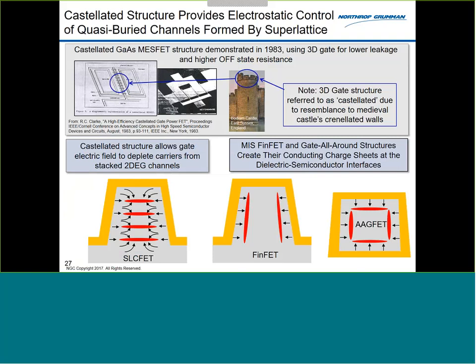In our device, we're using the gate here on these sidewalls. This guy doesn't do anything because of the shielding effect, right? So all my action is from these edges. If I just made a Schottky gate right there, this wouldn't work because I'm showing there's some depletion here, but essentially I'm making a practically direct connection between this gate and that connection.